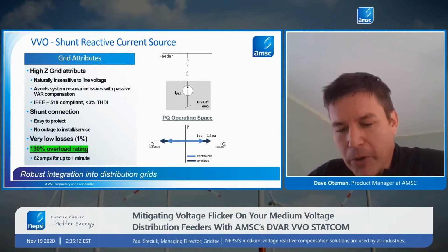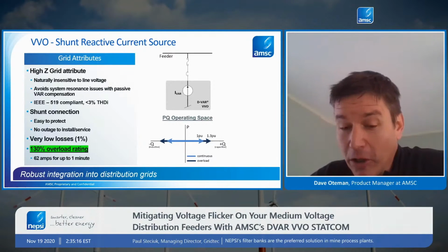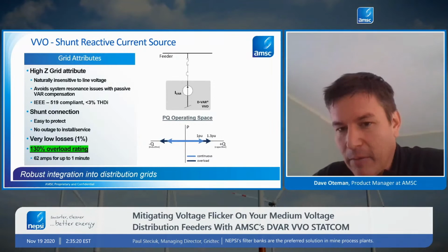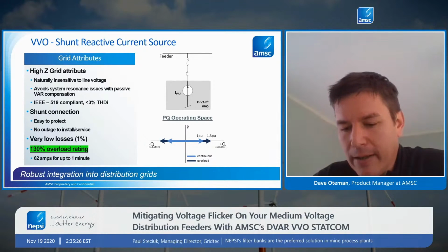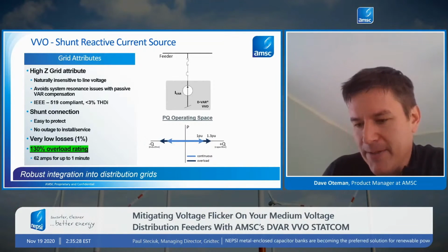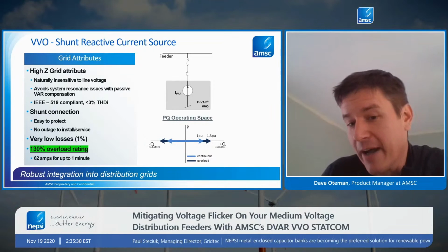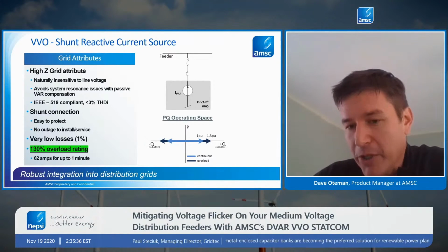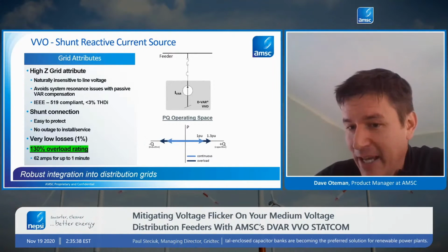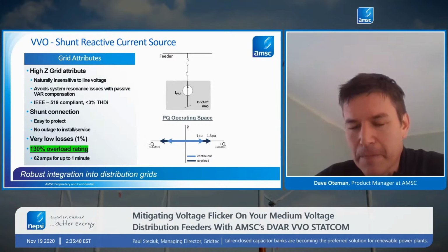So when we look at a motor starting event, a long motor starting event would be 20 seconds, and they're typically much shorter than that. So this overload capacity being available for up to a minute allows engineers to specify the overload rating in these applications for motors. So it helps to reduce the cost of the technology in this application even further.